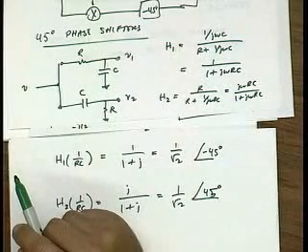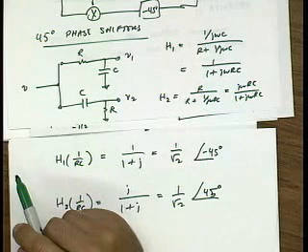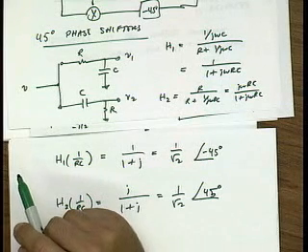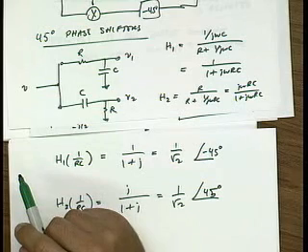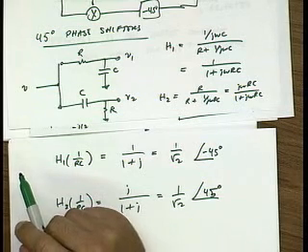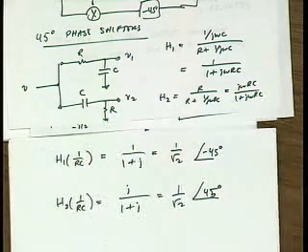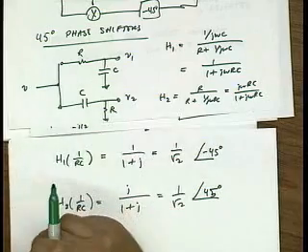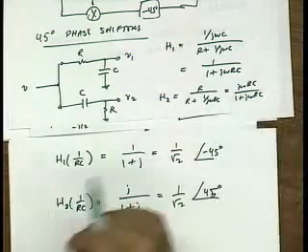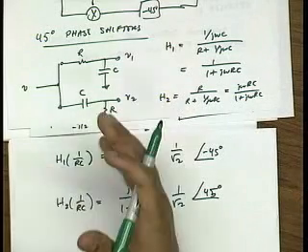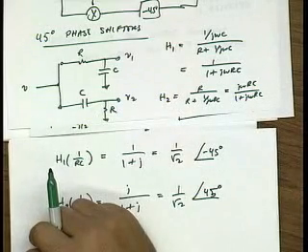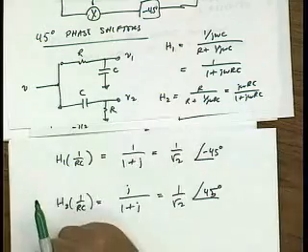I guess my question is, if we're not going to tune it, why not just have a longer piece of trace for one of the signals? Okay. Well, because to get a 90-degree phase shift would require a really long piece of wire. That's quarter wavelength. So if you think about it, at a gigahertz, the wavelength is on the order of centimeters on chip. So you need a quarter of a centimeter to get 90 degrees phase shift. No, but it's a totally valid question.